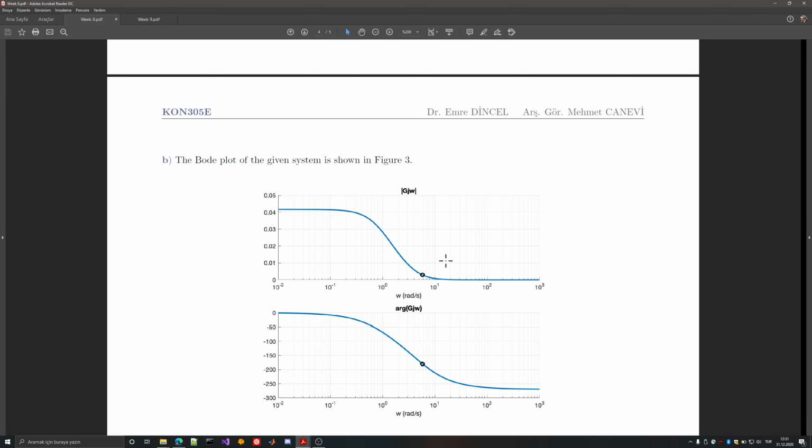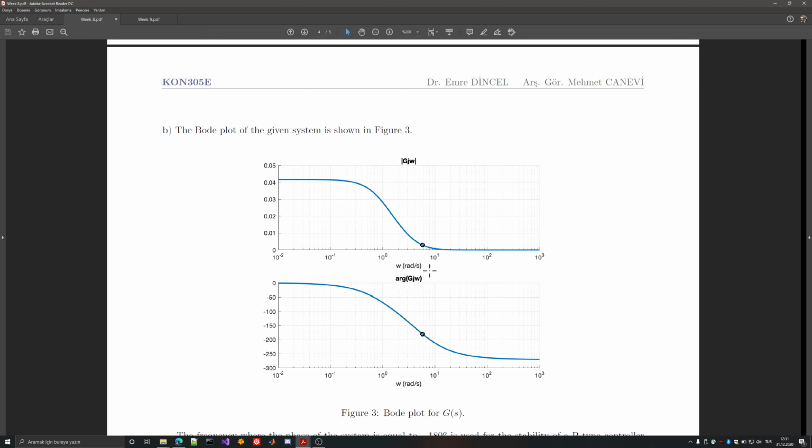Now the Bode plot is very important since it gives the same data, and it provides you the interval for any Bode plot. Keep in mind that the first method that we've used is the root locus method, and the root locus method needs a mathematical model. It wants you to define the poles and zeros and the gain of the system. You have to know exactly what they are. But in the Bode plot, if you have a Bode plot and you don't know where it comes from, or you don't know the system model, it doesn't matter. You can just use the Bode plot to come up with a gain or an interval for this gain.